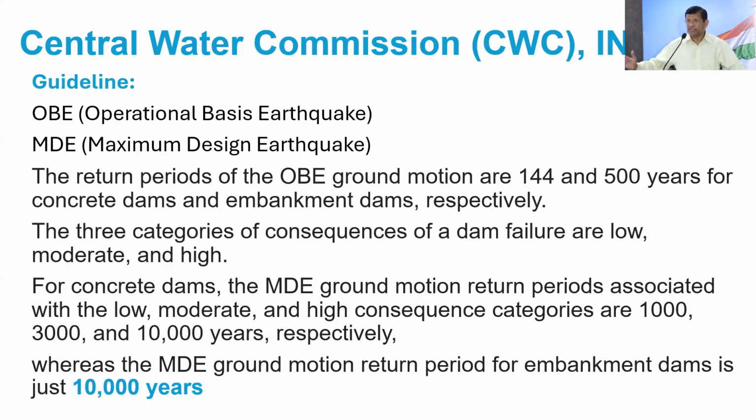But I mentioned these tailings designs are not over during the operational time, but continue after closure. After closure, they last for a long time. So we always have to consider the maximum design earthquake. For the return period, for operational design, their guideline says between 144 years and 500 years: 144 years for concrete dam and 500 years for embankment.